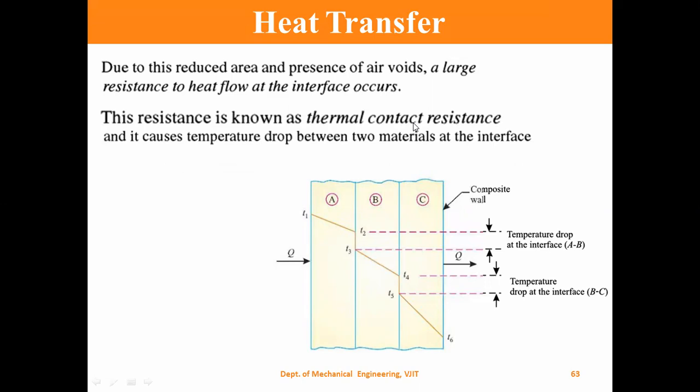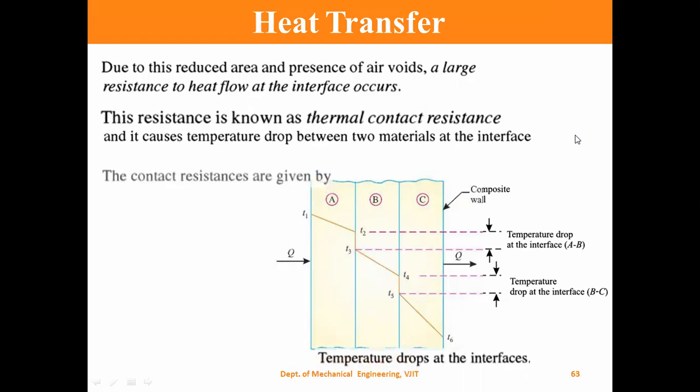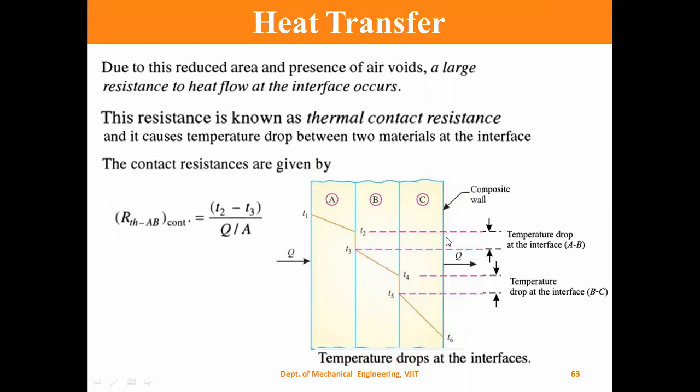And what is the importance of this thermal contact resistance? Due to it, the temperature drops between the two materials. There should not be any temperature drop, but because of this thermal contact resistance, the temperature drop will be there between the two materials at the interface. The contact resistance can be obtained by using an equation like this.